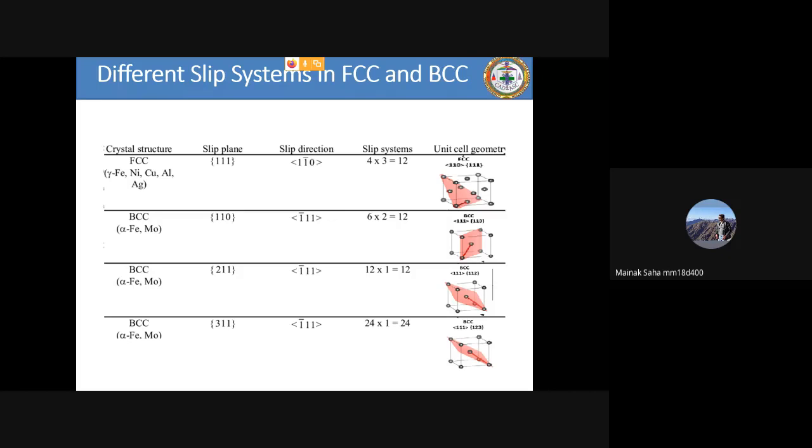Now carbon itself has a very small atomic radius as compared to iron atoms. If it is very small, there is a size difference. If there is a size difference, there has to be some lattice distortion. If there is lattice distortion, there has to be some strain in the material. Strain will harden your material, right? Because it will make it more difficult to deform that material. But why do we see it as a highly ductile phase?